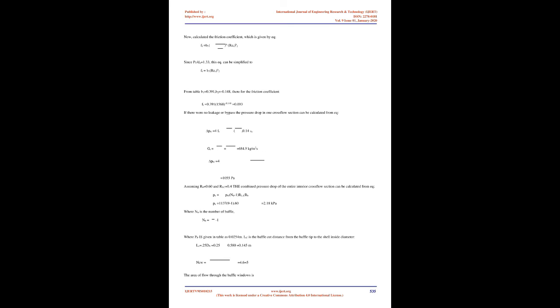7.2.6 Pass divider. A pass divider is needed in one channel or bonnet for an exchanger having two tube side passes, and they are needed in both channels or bonnets for an exchanger having more than two passes. If the channels or bonnets are cast, the dividers are integrally cast and then faced to give a smooth bearing surface on the gasket between the divider and the tube sheet. If the channels are rolled from plate or built up from pipe, the dividers are welded in place.